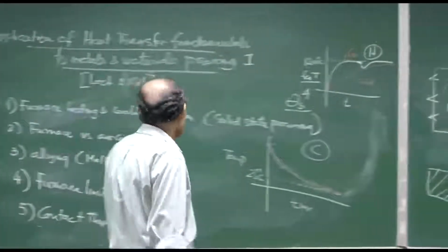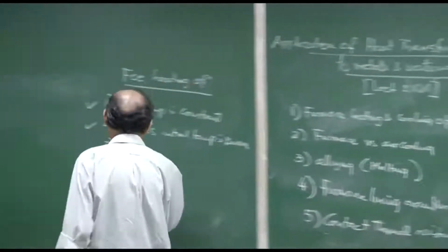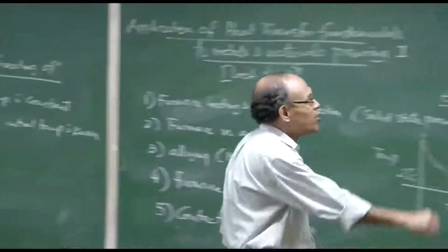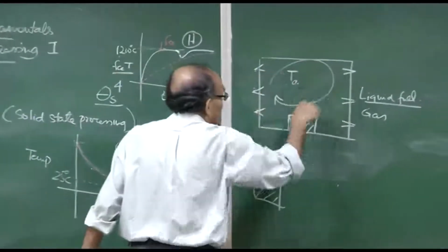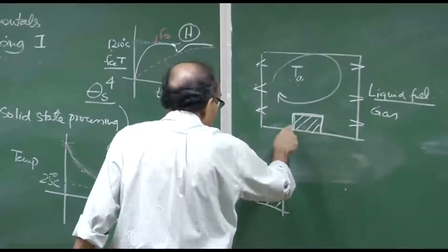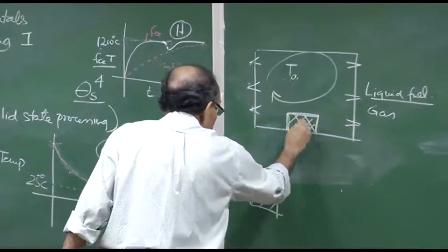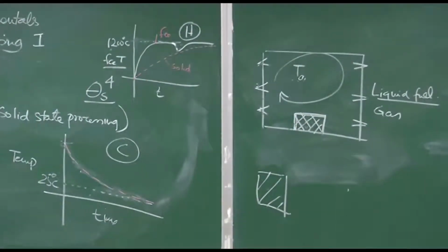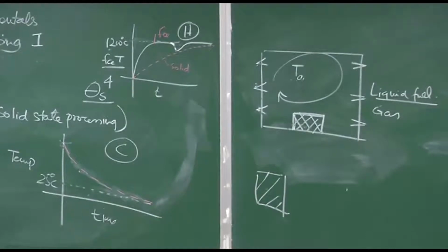So, we have to know the thermophysical properties: density, specific heat, thermal conductivity, etc. Mind that I am not interested in finding the temperature profile within the furnace itself, or the burning rate of the fuel. My interest is this particular domain, and if there are multiple ingots, I have to work out the radiation view factors also, as you all know.